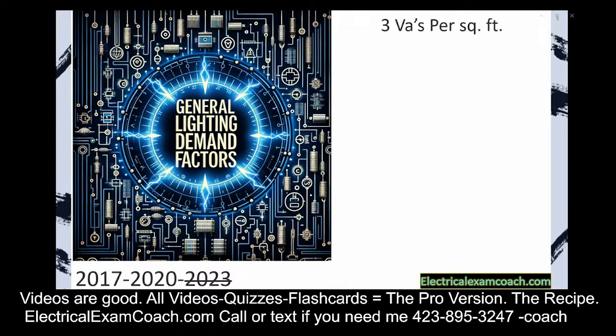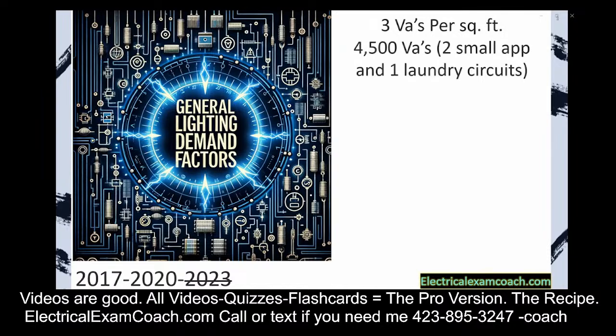At the beginning of the program, we learned that it was 3 VAs per square foot, and we had to add on the 4,500 VAs for our 2 small appliance and 1 laundry circuit. At the beginning of the program, I did not teach you about the demand factor for this because it's kind of complicated at face value, especially if you don't know what a demand factor is.